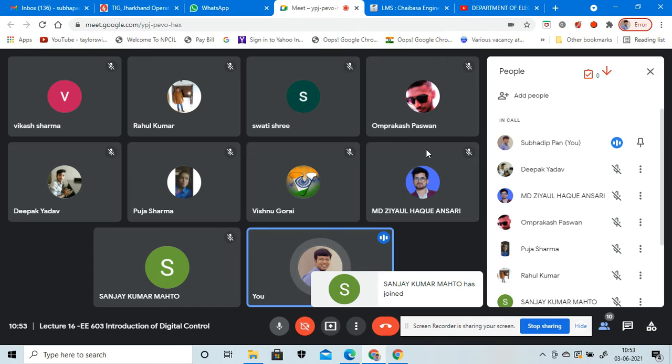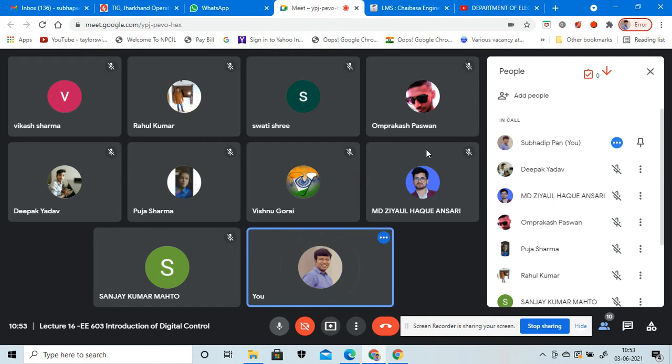So, a little bit brief about the quantization error again. I told you in the previous classes that a digital word is obviously finite. So for the conversion process in an analog to digital conversion, the output has a finite resolution, right? The digital output can assume only a finite number of levels. As our digital code should be finite, the analog number must be rounded. So that's why the quantization error is also termed a round-off error.